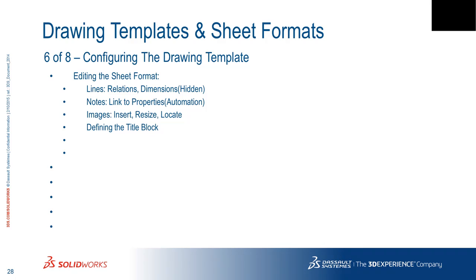The old school methods in AutoCAD, you would draw everything 1-to-1, and you would take the title block and a piece of paper and scale it up 4 times. And then when you went to print it, you would invert that on the print so it scaled it back down. Since SOLIDWORKS does it different, when you go back to that old method in AutoCAD, that gets to be a scaling issue that you have to deal with. And I really don't know a good way around that.